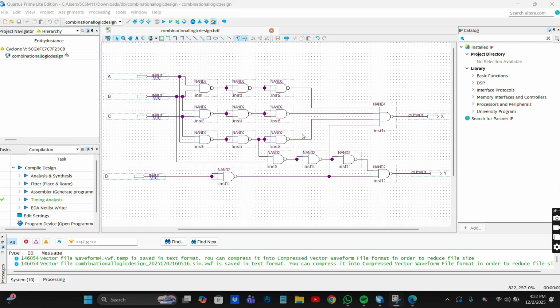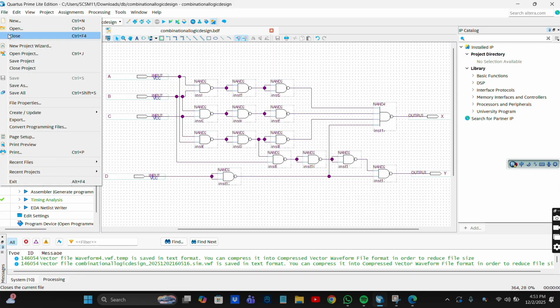To achieve this, we convert all the basic logic gates into NAND-only versions. An AND gate can be replaced using two NAND gates, a NOT gate can be created using just one NAND gate, and an OR gate can be built using three NAND gates. Then we can simulate the logic gates to check if they produce the same result as the basic gates.